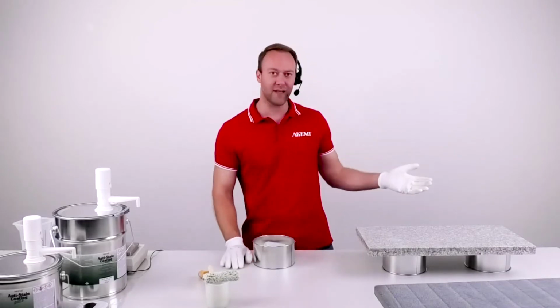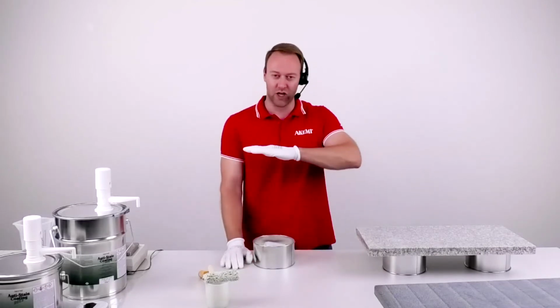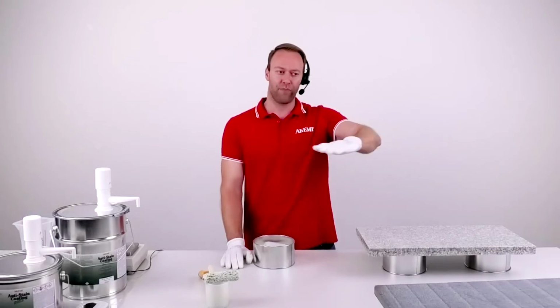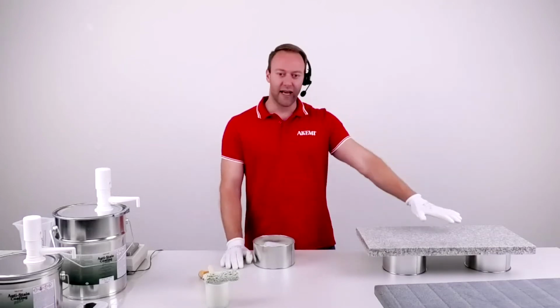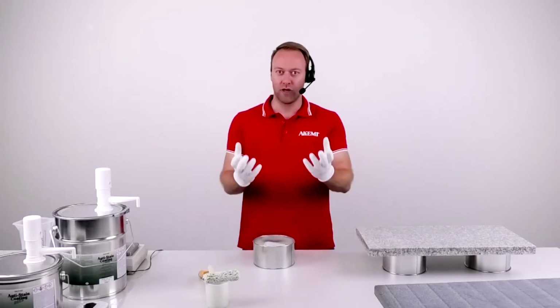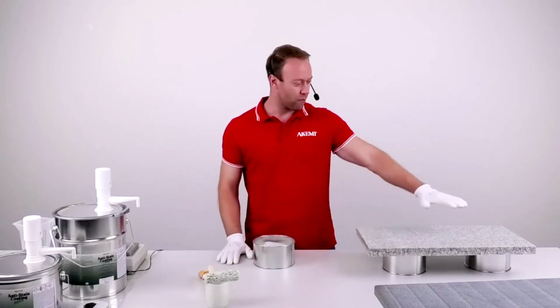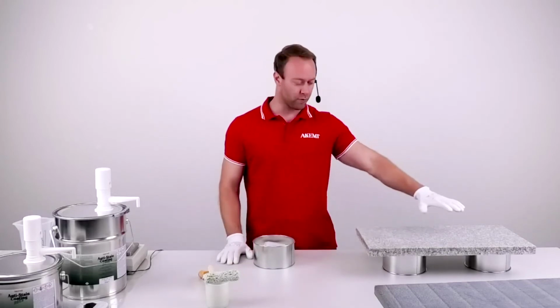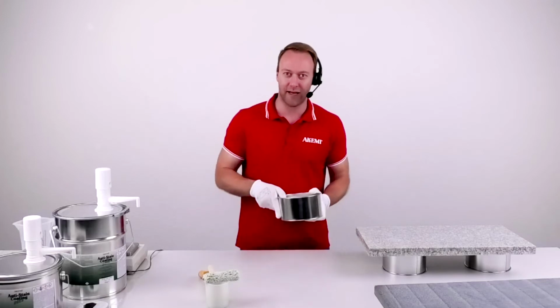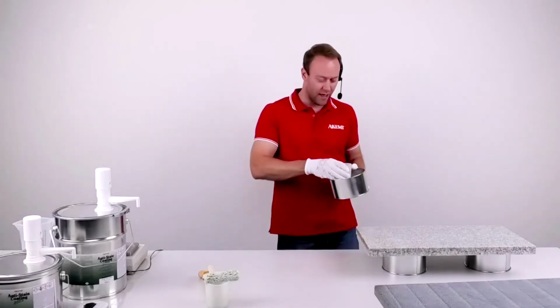If I have installations like a tombstone, where I just put my monument into the soil, then I can leave it like that, because I don't need adhesion. It will block the soil and the stainings from the soil. But when I have fixed installations on mortar, I need the sand. So I do that now. I just sprinkle a little bit of quartz sand on top of the surface.